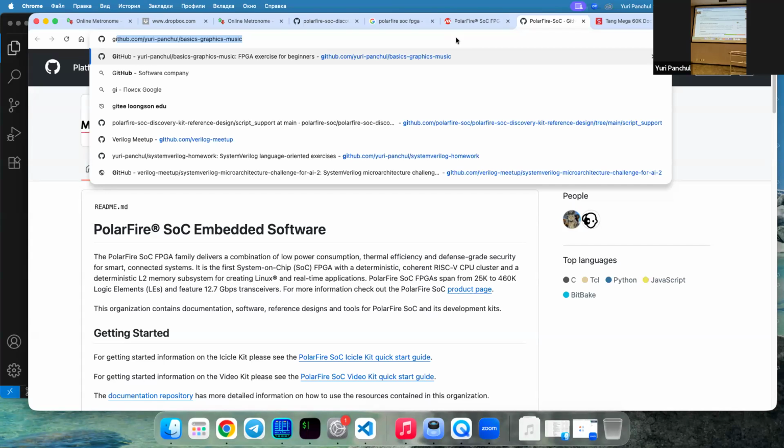Also with Artix 7, several people attempted to do this with that board, but they didn't do it to the end properly. So I want to do this to the end. But one thing with the Artix 7 board, this TM1638 says that its power VCC is 5 volt.